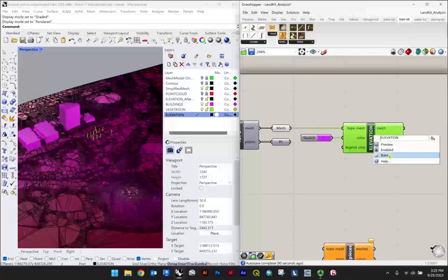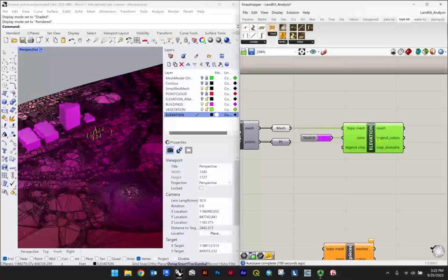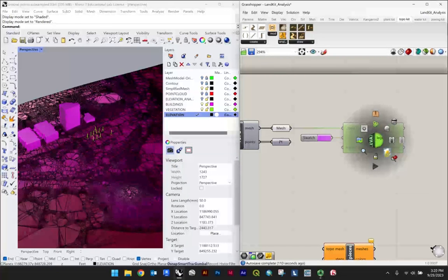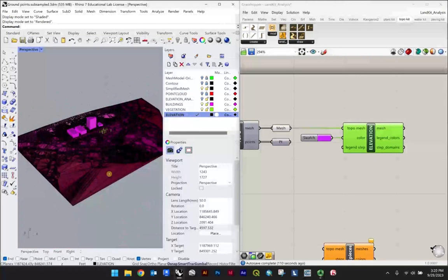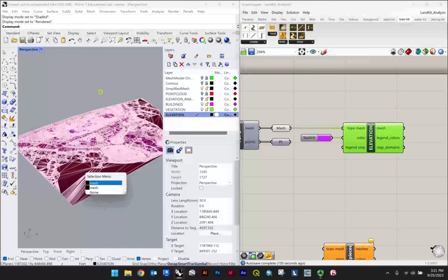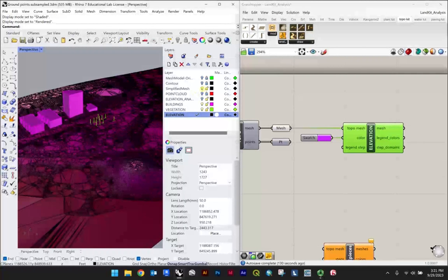I had shown you the right-click, bake, and this allows you to choose the attributes of the bake, as in which layer. You could also hover over this, hit that scroll wheel, and hit bake, and it'll do it slightly quicker. In this case, it just uses the layer that you're on. So that would be one way to perform this function. So just to kind of see what's going on, I could take my simplified mesh and turn that off.